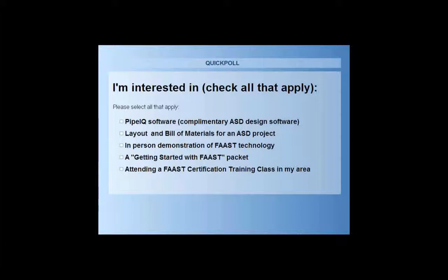What about length of pipe restrictions? Is there a maximum length of pipe? Yep. There's a couple we recommend as maximums, and these are rules of thumb, just so if you're trying to design or quote a system, you have an idea how far you can run these. If you're doing a single pipe run with no T's or anything, let's say if it's linear or in a serpentine fashion, the maximum run is 262 feet of pipe. Okay.